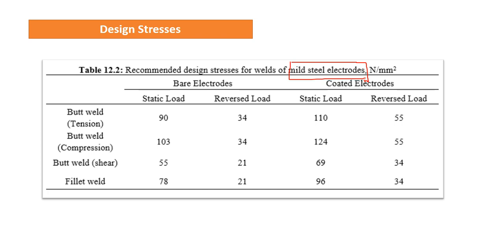So that all depends on the strength of the weld. In the welded joint case, we can have efficiency of welded joint sometimes more than 100% if the weld that you are applying has more strength as compared to the strength of the plate.